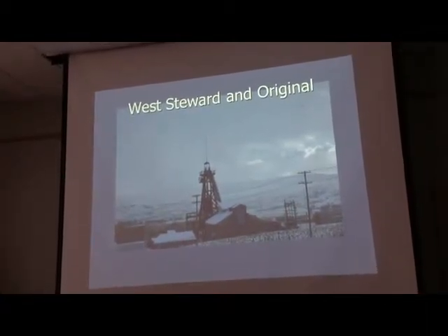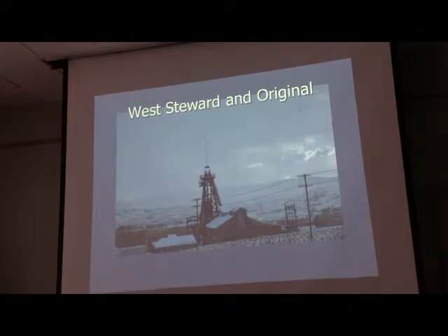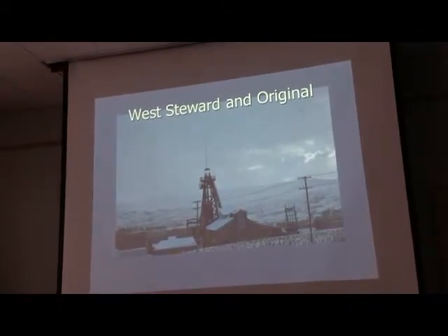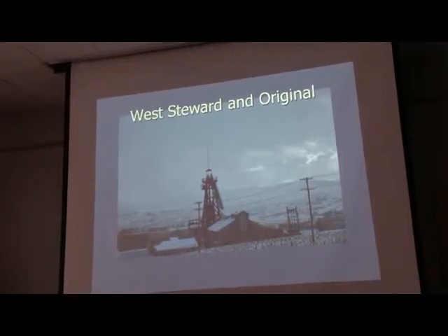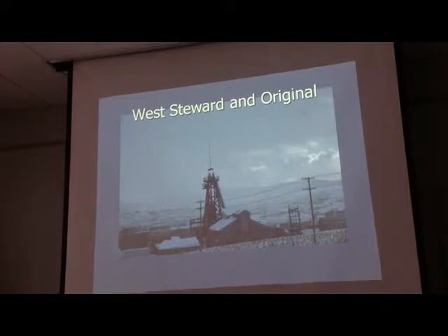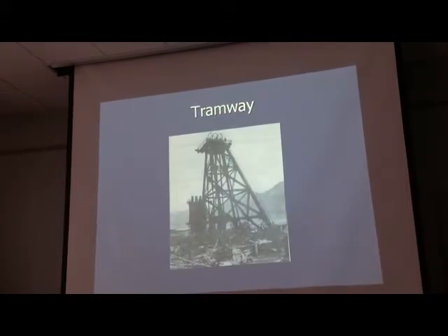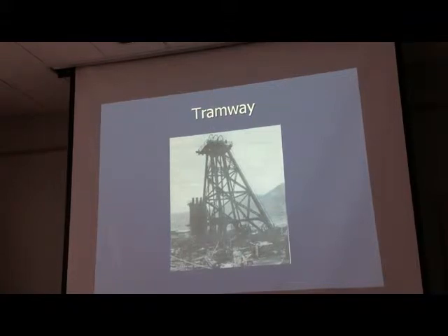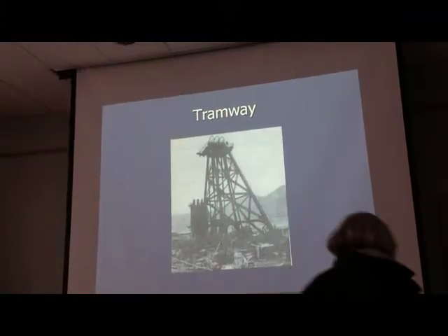These are 127 feet tall. They're actually taller than the Badger, or the Belmont, or the Mountain Con. And they are, once again, here you don't have the heavy post mount sheave bearings. You've got the girder mounts, and these are the type that you can modify if you needed more sheave wheels on the top. The tramway was just a 94-foot version of the same design by Gillette Herzog with 3 on top.